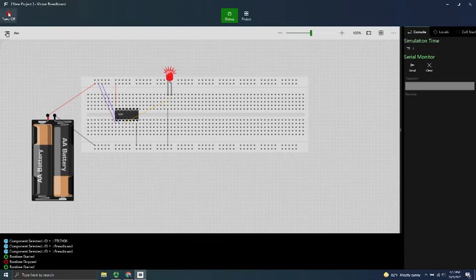All right, so this is how we use a breadboard. And if you need to come back and review the video, please do. Remember that all of these are connected together. On a real breadboard, they're all connected together. On the simulator, it looks like just half of it's connected together. And this entire row here is all connected together. So I can make this entire thing ground all the way across. And I can make this bottom row power by hooking up power here. And so I can tap into power anywhere there in that node, like a junction box.